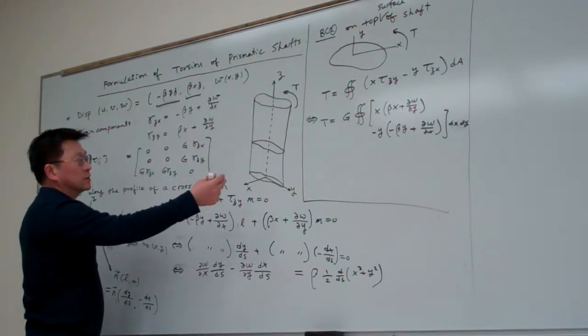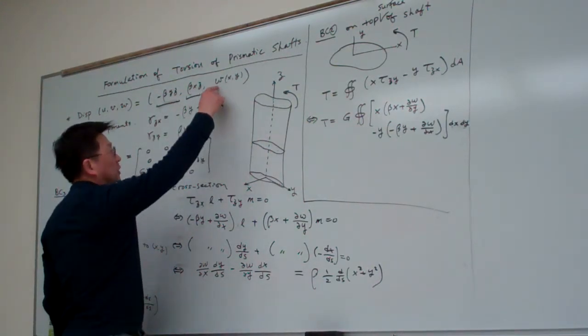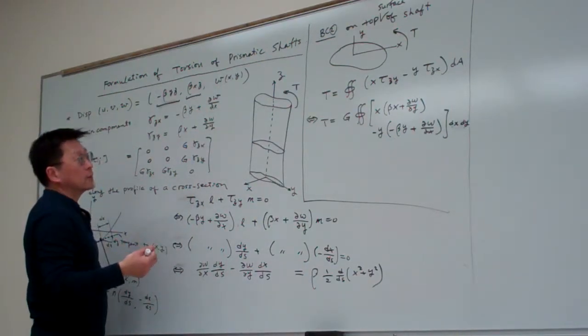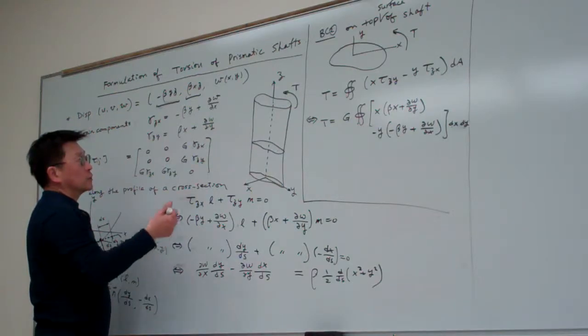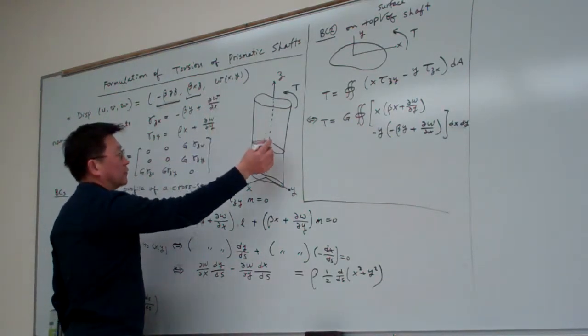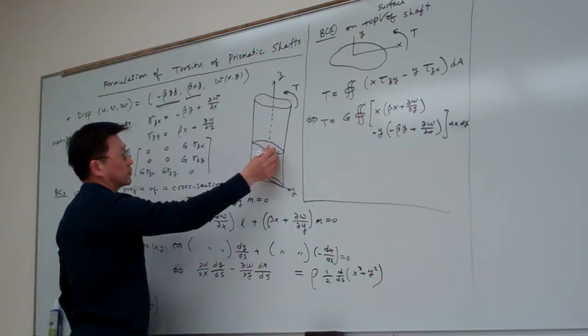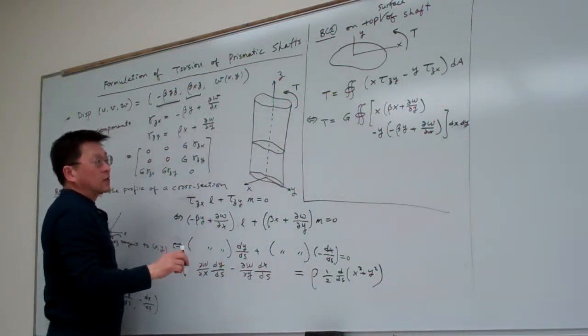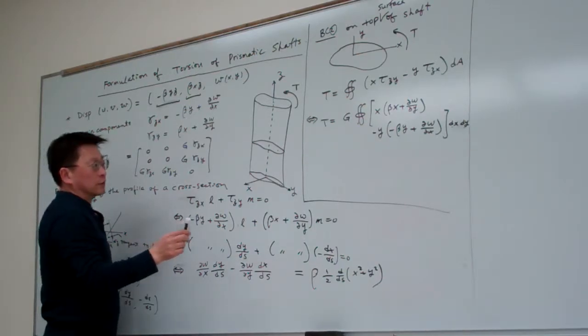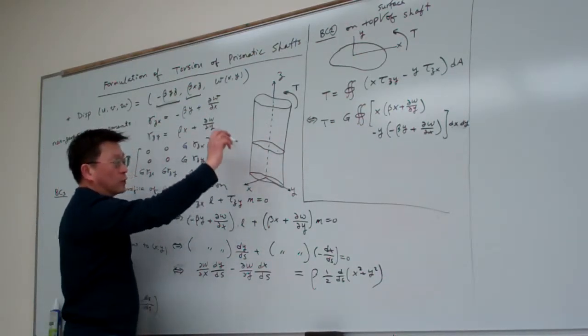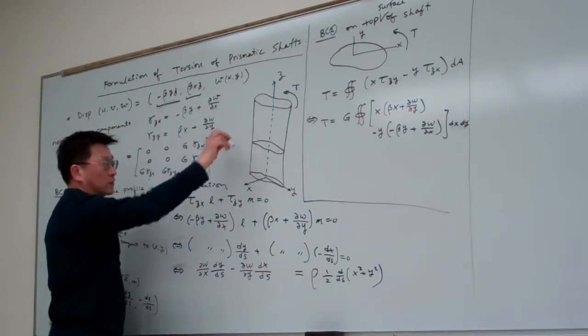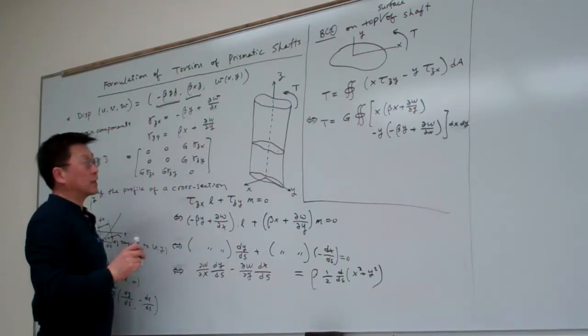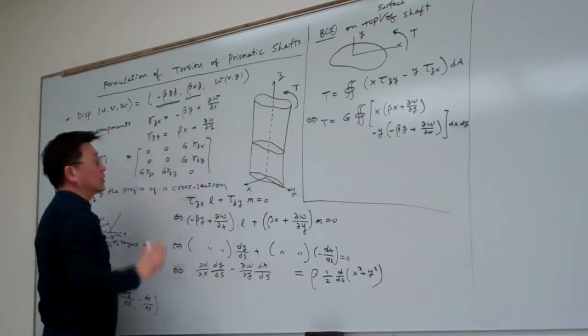And for the displacement in the third dimension, it's called W, the warpage, or warping. We assume the warping is only a function of the point in the cross section, but is not affected by the level. So that means if a warpage occurs at any cross section, the warpage is the same as at the other ones. Okay, so that is another assumption here.